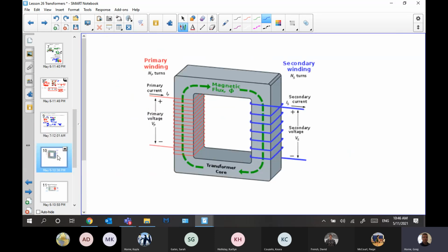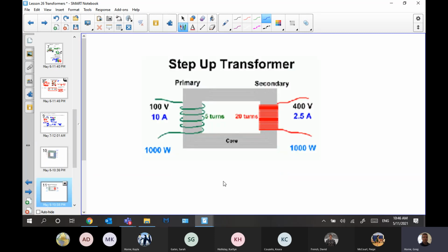So totally normal. So you'll see it written like this, where you've got primary winding and secondary windings and so on, right? Other examples here. So they're showing if you have 100 volts applied, first of all, let's analyze that, and it's 5 to 20, right? So you're like, oh, that's times 4, right? So check it out. There's your 400. This is just a Google image. We're just confirming that we're actually checking right now to see if they're right. Because it's supposed to be 4 times as much voltage, so there it is.